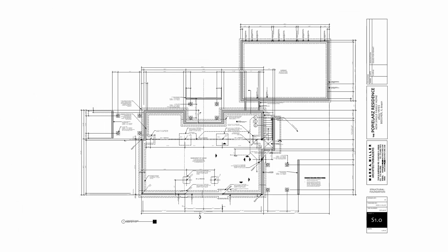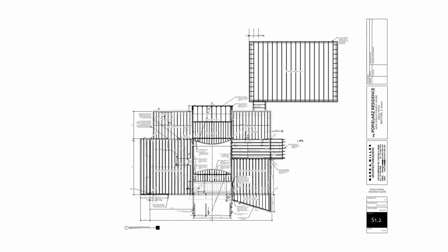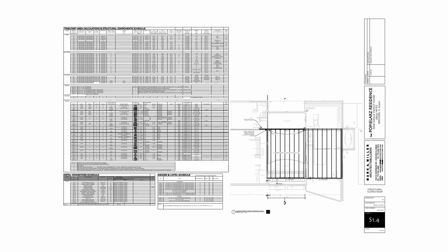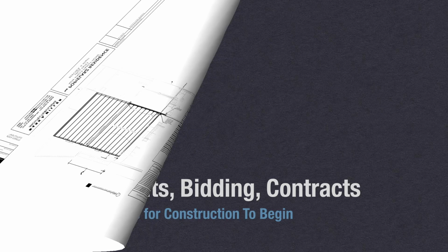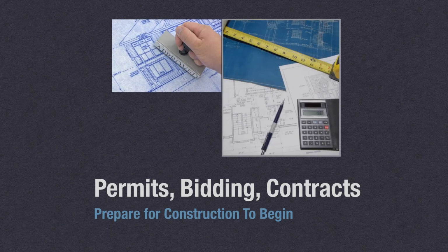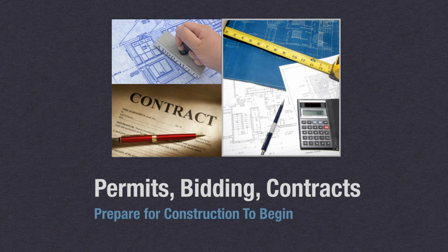And then structural work, so the concrete for the footings and foundation walls with all those dimensioned properly. Framing plans describing the size of each of the framing members, their spans, their depths, their thicknesses. Beam schedules, metal connector schedules, headers and lintels, and that rounds out the construction documents.